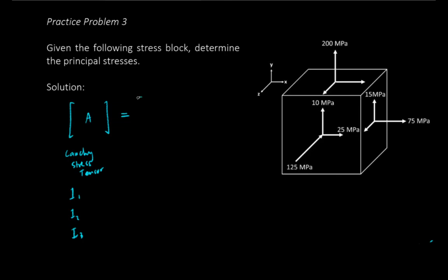The first component is your hydrostatic stress, wherein one normal stress is applied equally on all three directions. For this case, let's call that stress value lambda, and I'll show you later why I chose the symbol lambda. So there are no shear stresses, and there is only the lambda value present in all three normal directions.